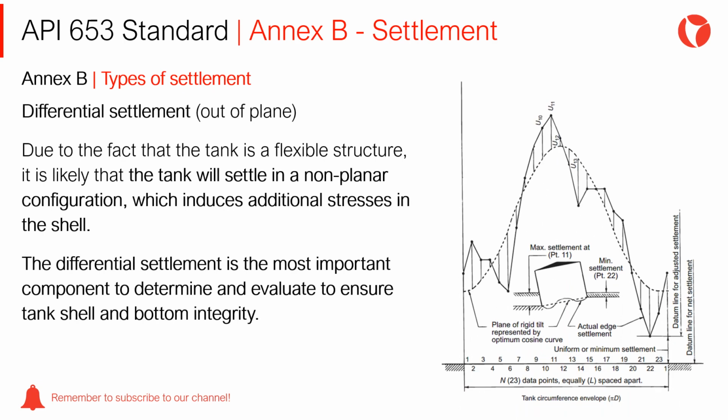Differential settlement out of plane. Due to the fact that the tank is a flexible structure, it is likely that the tank will settle in a non-planar configuration, which induces additional stresses in the shell. The differential settlement is the most important component to determine and evaluate to ensure tank shell and bottom integrity.